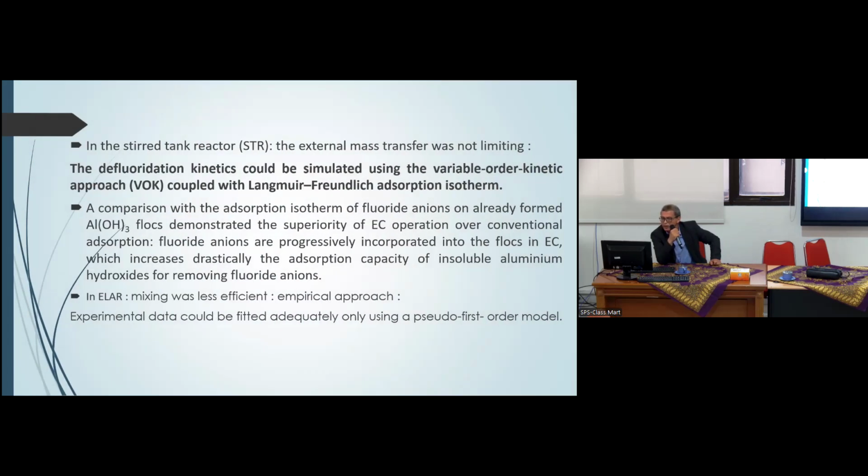So in the side reactor, the external mass transfer was not limiting. The fluoridation kinetics could be simulated using the variable order kinetics. A comparison with the adsorption isotherm of fluoride anion on already formed flocs demonstrates the superiority of the electrocoagulation operation over conventional adsorption. In the external reactor, the mixing was less efficient. With the empirical approach, the experimental data could be fitted adequately only using up to the first order model.